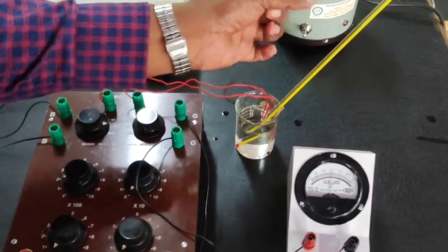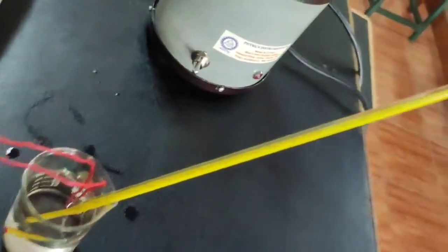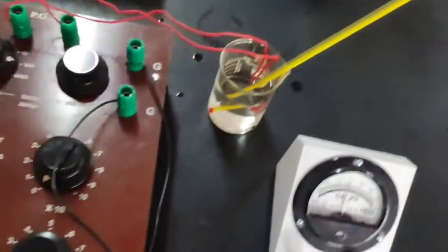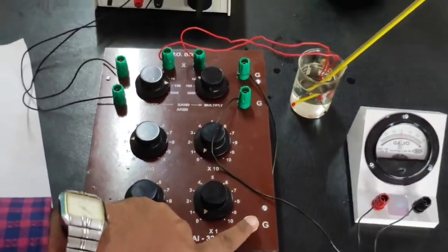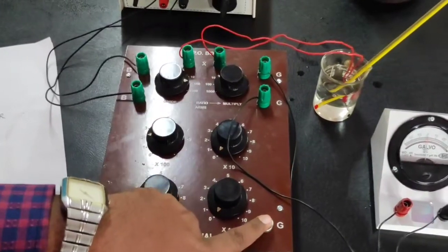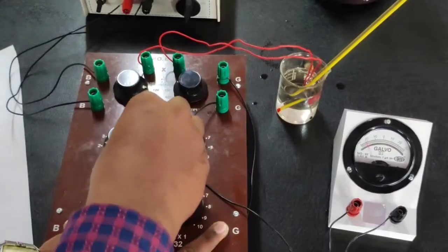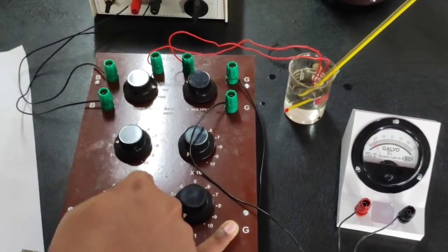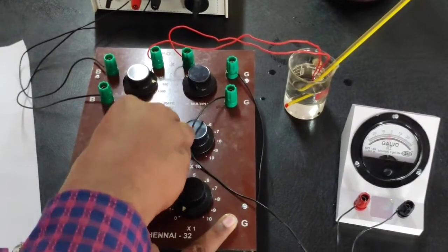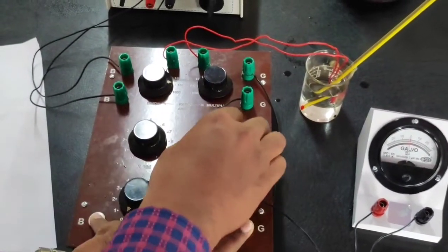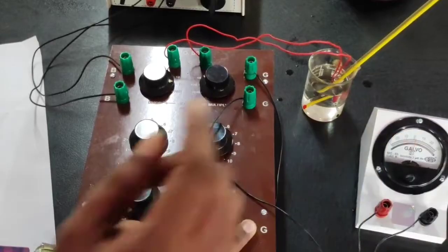Now it is nearly 83 degrees. I'm going to start at 80. At 80 we have to measure how much resistance is on this dial. To connect the circuit, we just press these two buttons, and the galvanometer will show a deflection. We have to nullify the galvanometer by adjusting the values of R, that means these dials. I increase the 100 and this 2. Now it is completely 0.